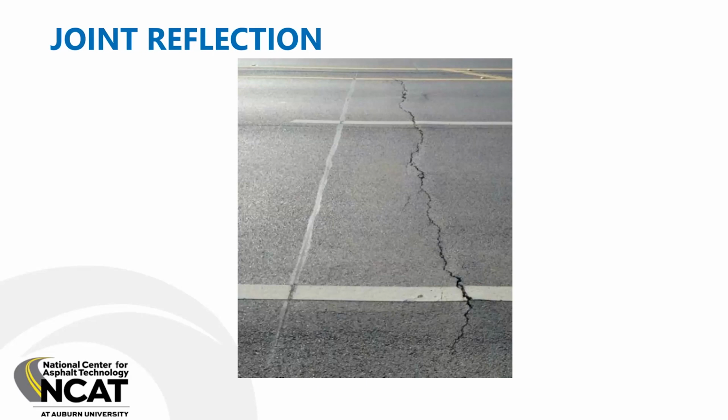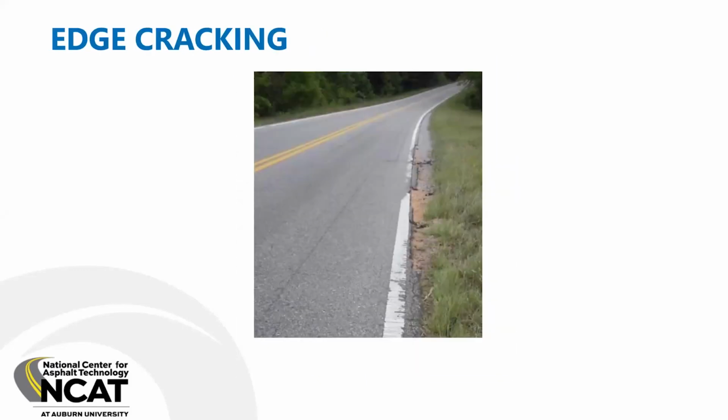And so that is not a thermal crack. That is not a fatigue crack. That's a jointed concrete reflection because of that misalignment. Another type of longitudinal cracking is edge cracking, and this is described in the LTPP manual.